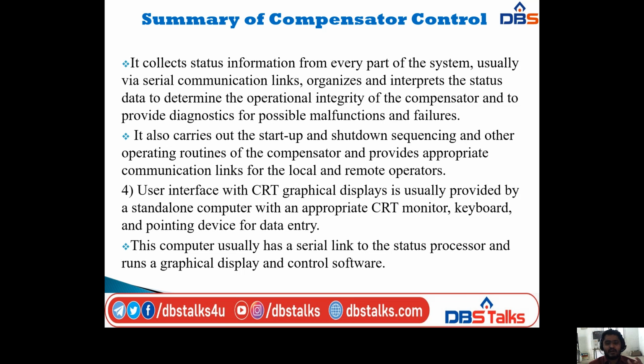It collects status information from every part of the system, usually via serial communication links, organizes and interprets the status data to determine the operational integrity of the compensator and to provide diagnostics of possible malfunctions and failures. Diagnostics means analysis of possible malfunctions and failures, that means faults. It also carries out the startup and shutdown sequencing and other operating routines of the compensator and provides appropriate communication links for the local and remote operators. That's why we are using the supervisor.